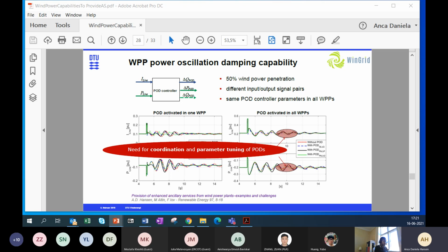For example, the controller can send these requirements, these delta signals, to each individual wind power plant in a proportional way, namely according to the size of the wind power plants. I think that we have done it like this, if I remember it right. But of course, a more complex, detailed dispatchment can be done.